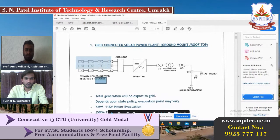Once you connect the modules, the SMB as well as the SCB come into the picture. It means string monitor box or string combiner box. So why are we using this equipment? Because there are multiple wires and connections coming from the solar modules. The inverter has no facility to take all these wire connections as multiple direct inputs, right? So we put in the string combiner box, or we can say the string monitoring box also, right? So here is the inverter. There are two types of inverter currently available in the market.